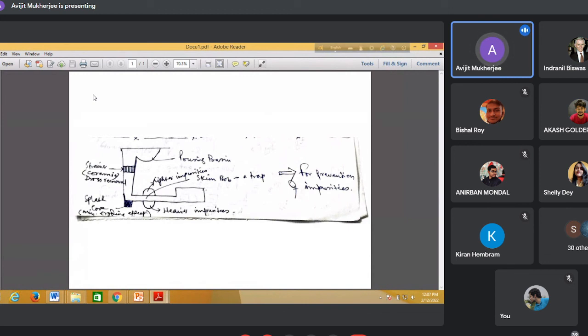This is the mold cavity. This is known as ingate. Ingate. There may be many more ingates, not a single one. Later on we shall discuss. And on the runner, so there are strainer, splash core, and another trap. Trap. It is known as skim bob.